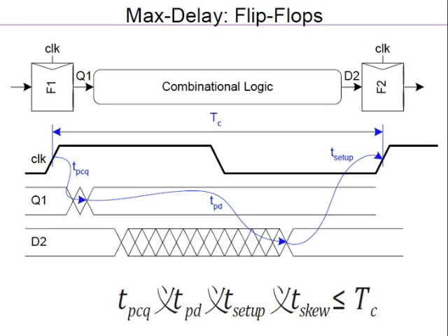This is like when you are entering an elevator and the elevator door automatically closes. You want to make sure all your body parts are inside before the door closes. It's kind of like that. You want to make sure the data is all properly inside, and then the clock edge happens and captures the data. That margin is called T setup. If you come before T setup, you are captured properly, but if you come within the T setup, it might not capture it properly.